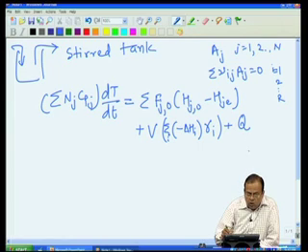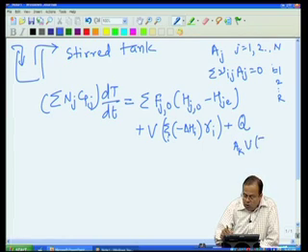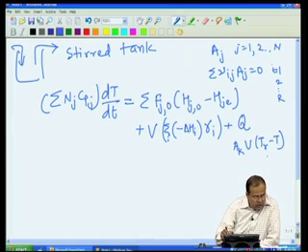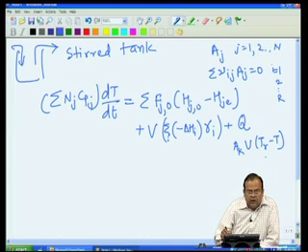So, Q, for example, we can also write as A_h U (Tr minus T), where A_h is the area for heat transfer, U is the overall coefficient of heat transfer, Tr is the temperature of the coolant or the heating media that is in the jacket, which is transferring heat, adding heat, and T is the temperature. So, this is the energy balance for a stirred tank reactor.